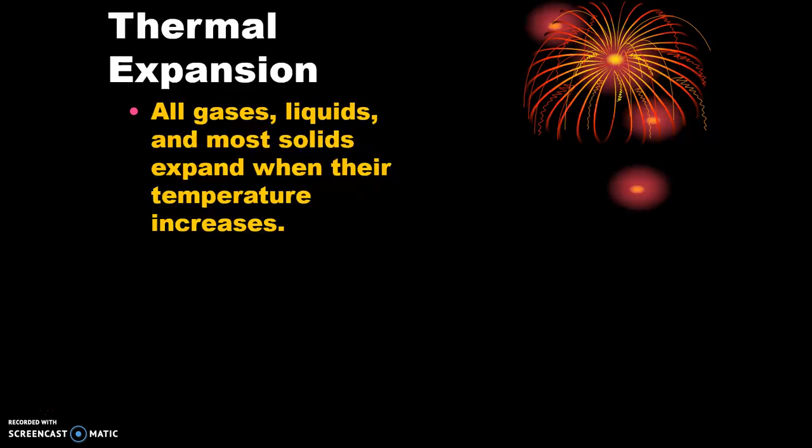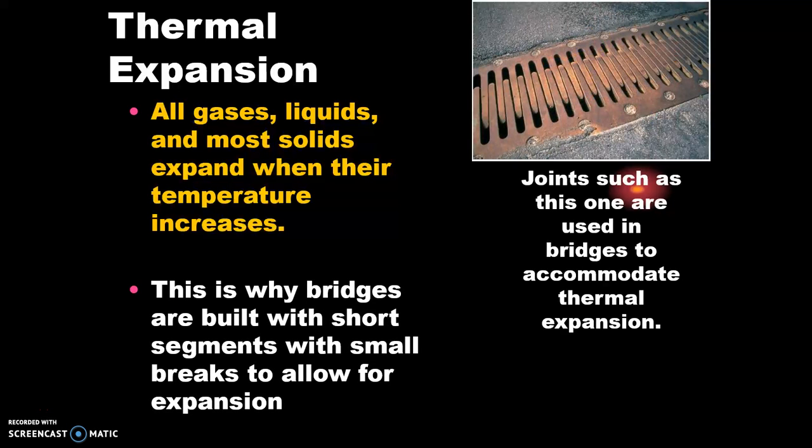And this is all based on the idea of thermal expansion, where if something has a higher energy or a higher temperature, it's going to expand and take up more volume. So all gases and liquids do. Most solids expand when their temperature increases. This is why we have bridges, structures that have kind of these little gaps, or you can see here this little joint here that allows that thermal expansion and contraction to happen so that you're not going to have buckling and any kind of damage happening to your structure when that happens.